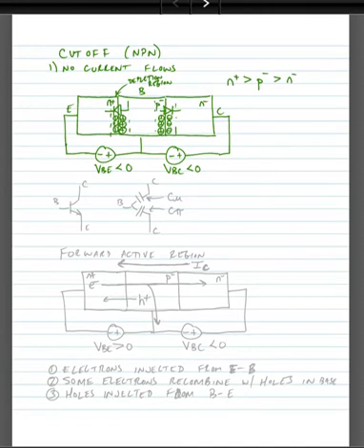But we have an open circuit here, at least in terms of a DC circuit, so our symbol could basically be replaced with an open circuit. Or if we were looking at AC analysis, these depletion regions would look kind of like capacitors, so we could put capacitors between the base and collector and base and emitter. So the base to emitter capacitor is called C pi, and the base to collector capacitor is called C mu.